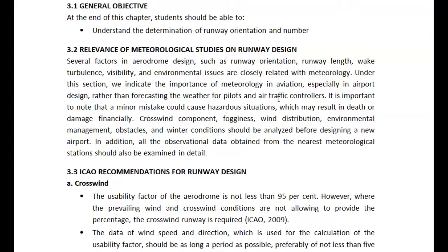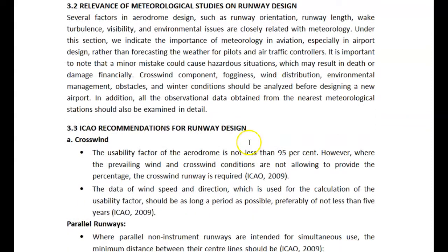A crosswind component, fogginess, wind distribution, environmental management, obstacles, and winter conditions should be analyzed before designing a new airport. In addition, all the observational data obtained from the nearest meteorological stations should also be examined in detail. So we look at the ICAO recommendation for runway design.